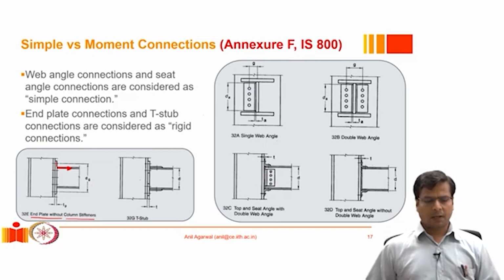Okay. Another variation of the same method would be, instead of welding an end plate to the beam end, we can use two T stubs. So these are basically two T sections, and the web of the T section is bolted or welded to the beam flanges, and then the flange of the T section is again bolted to the column. So when this kind of a connection is subjected to a moment demand, let's say in this direction, it is subjected to a moment.